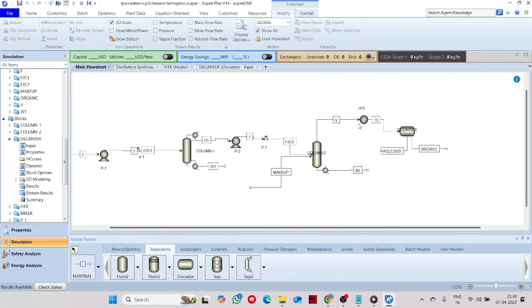And before you connect this one here, we will use the Newton method to converge the simulation, and in the advanced sheet we will use stable math, because as I said earlier, it is a three distillation boundary synthesis flow sheet. So we will use the Newton method here. This is a somewhat complex flow sheet compared to the other heterogeneous distillation columns.